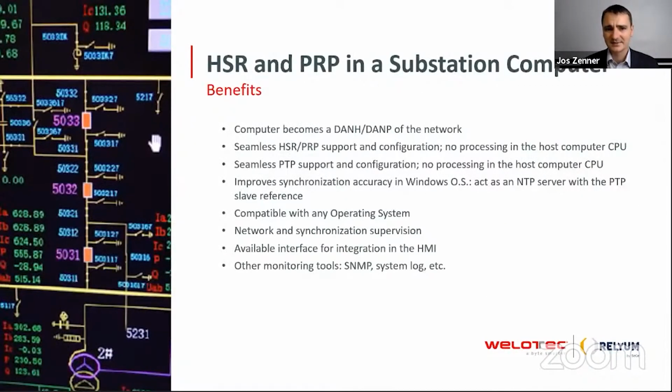So what does it mean? The computer becomes a dual attached node for HSR networks, or if you are using it mainly in the station bus, it becomes a dual attached node for PRP networks with hardware support, so you don't need to take care of the software itself.